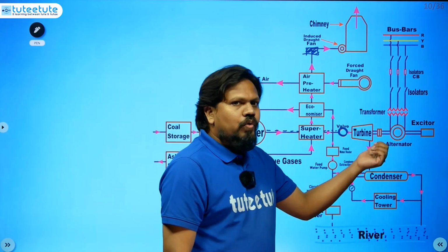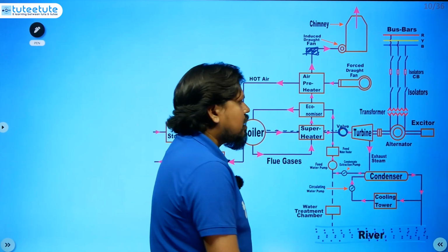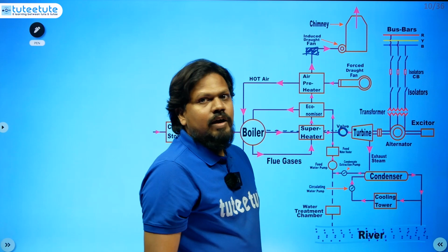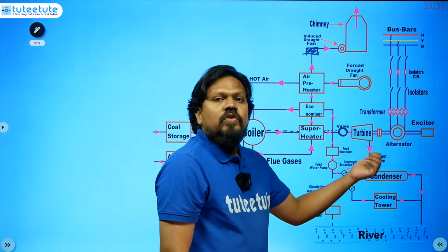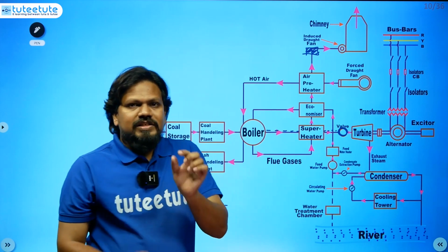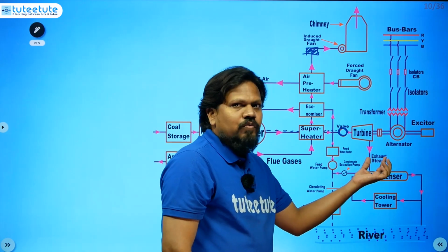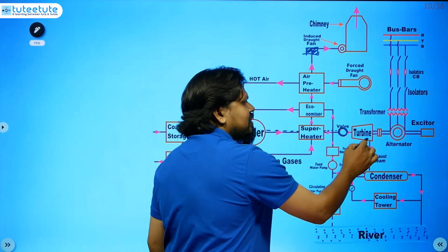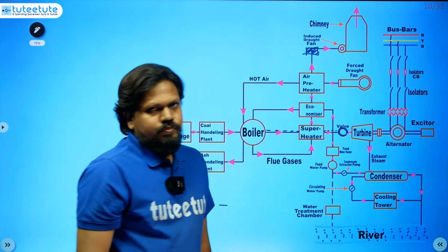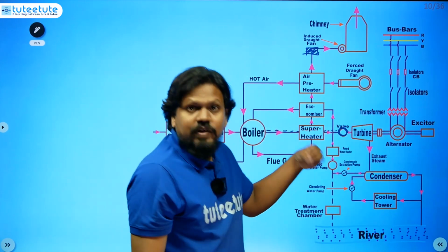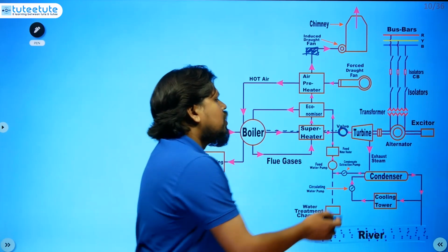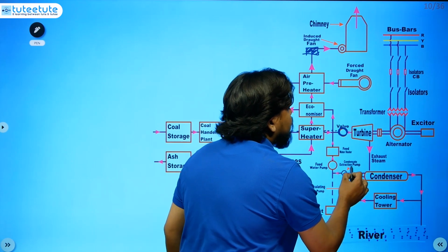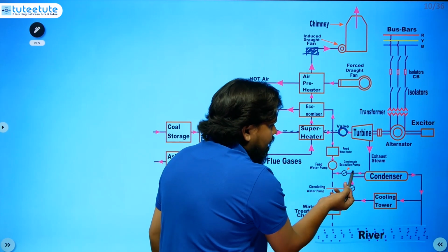You may get a doubt: why this used steam? Can we use this steam again or not? This used steam we could directly use in the boilers, but this used steam will have some expansion, and some bubbles will be coming. We cannot directly use it, because previously the pressure and high temperature were there, and once it has been used, they may drop down. Understand? So this steam we cannot directly use again. That's why we have to convert this into hot water. The condensate extraction pump is there, and using this pump, we have to take that hot water.